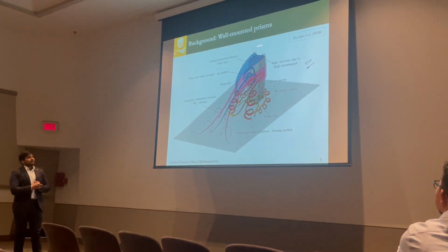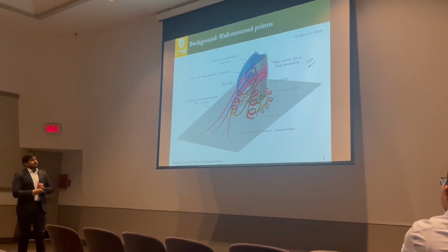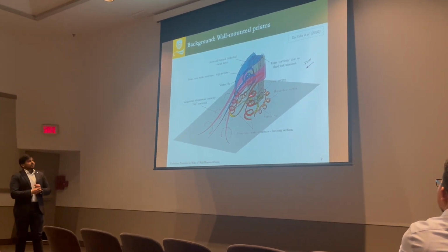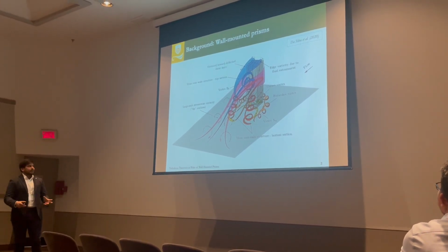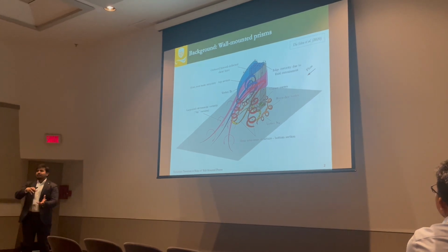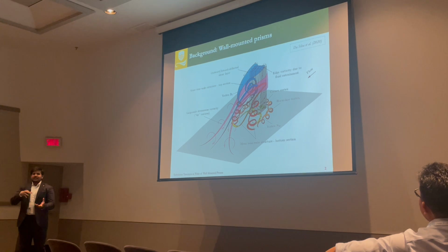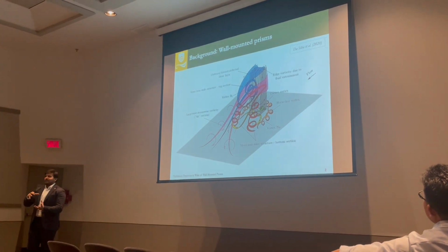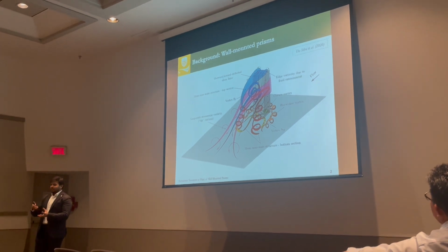Now, the wake of wall-mounted sharp-edged bluff bodies features a lot of different vortices, such as free-end vortices from this surface called the tip vortex, junction vortices from here called the base vortex, and this horseshoe vortex looping around the bottom surface. The intermingling of all of these different vortex structures behind the prism leads to formation of different wake topologies, such as arch-like or Karman-like wake topology.